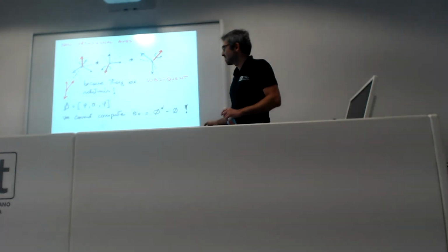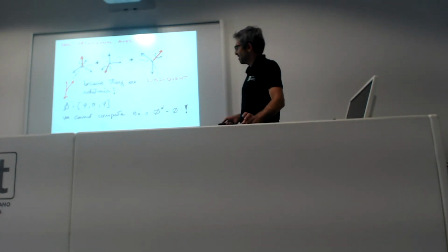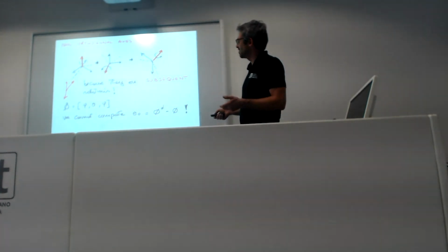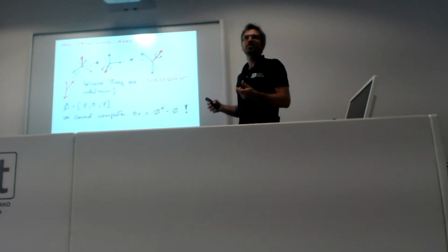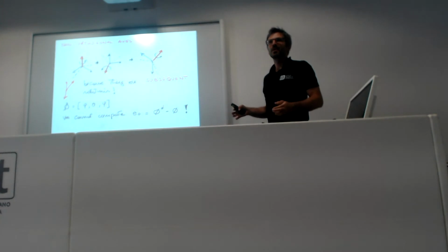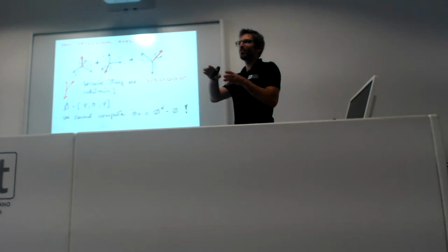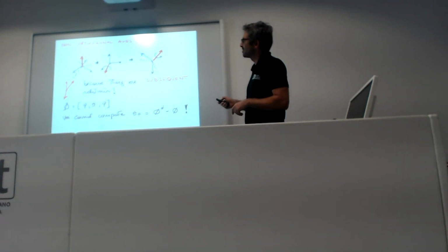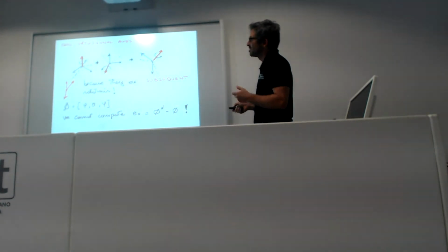So, in essence, at the beginning of my PhD, I was computing the orientation error with the Euler angles. So I was saying, okay, desired roll pitch yaw minus roll pitch yaw, get the error, map into torque, and that's it. That is wrong. It's not wrong if you have small orientations, because this effect is not so visible. But whenever you get big errors, this is not correct.